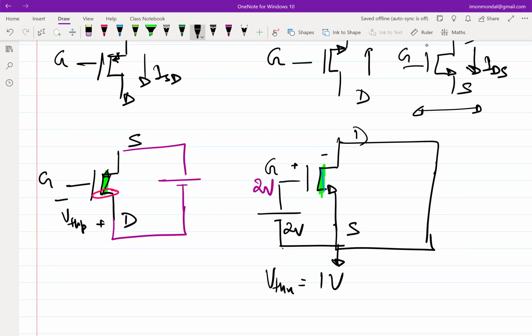That is 2 volt, right? So this is seeing 2 volt. And you only require 1 volt to get the channel on, right? So which means that it's an overkill. So now if I increase the drain voltage to 1 volt, what is this? This now becomes 1 volt, right? So if it is 1 volt, that sliver of MOSFET which is connected to the drain junction, do you think that is having channel charge or channel charge vanished? It is just going to vanish.